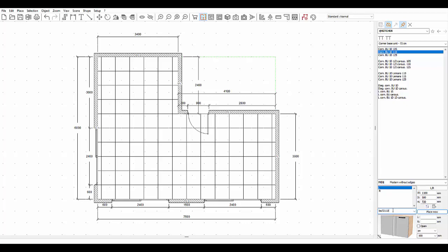Once you have found it, you can modify its measurements, if the manufacturer allows it. You can again enter the height placement, above or below, as well as placing the object from the left or from the right side of the wall. Drag and drop the image of the object in the angle you want to place it. Don't hesitate to put the element in the angle, the system will correctly place it thanks to the magnetization of